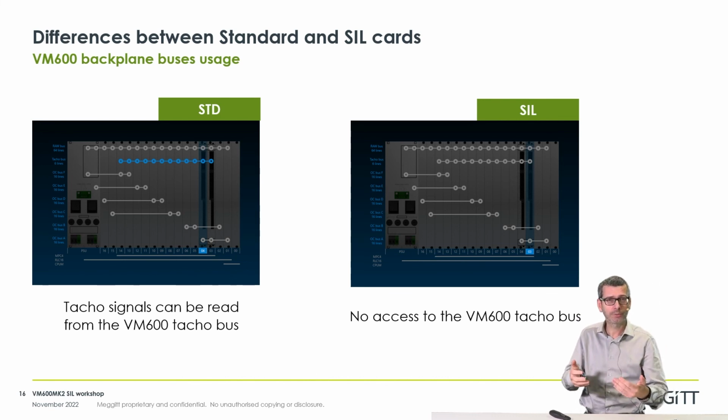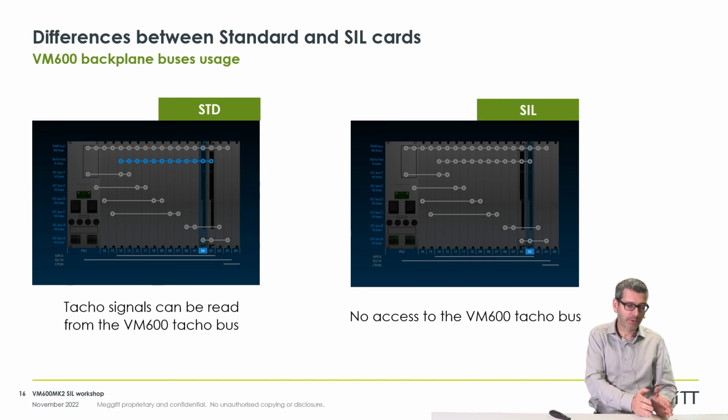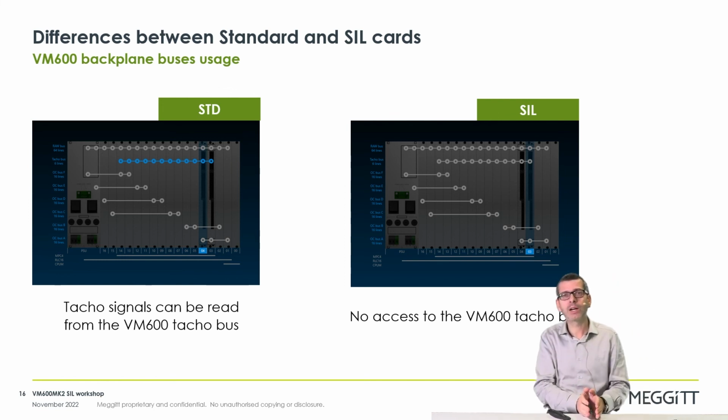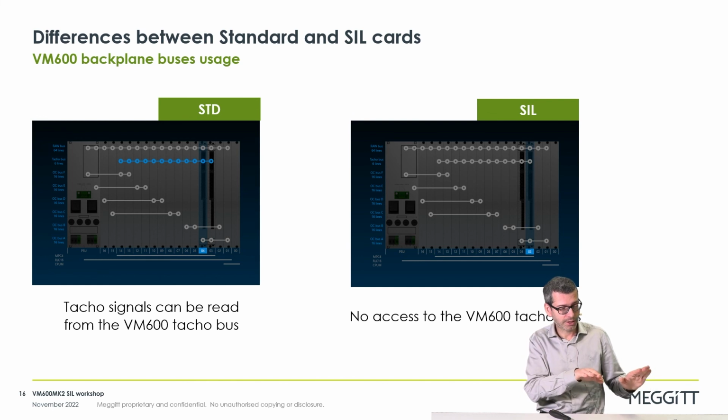That allows doing protection in one MPC4 card, with the sensors connected to the MPC4, and then the signals are sent to the RAW bus and can be received by an XMV card that will do the condition monitoring function. In that way, we have segregation at the level of cards between protection and monitoring.